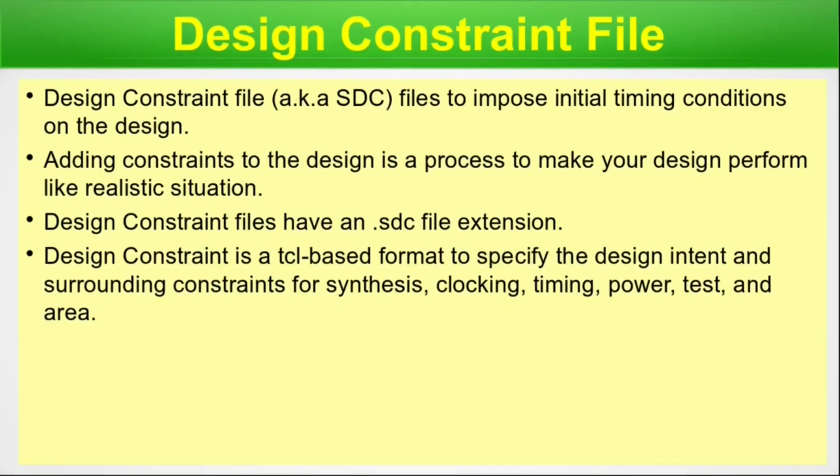So guys, all these Tcl commands are custom-made Tcl procedures, and they are very much application-intended, so that one particular command will do one thing. If you know Tcl, you will very easily be able to write the Tcl constraints based on the definitions that are provided in the manual. I think in upcoming examples, your mind will be very clear that these are Tcl commands and how we are using them.